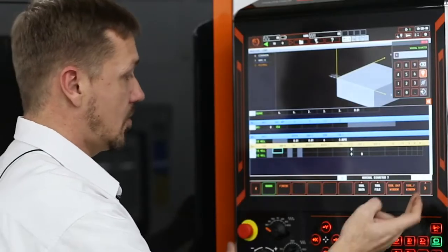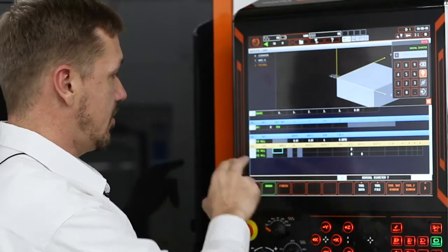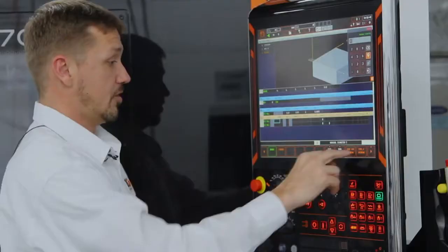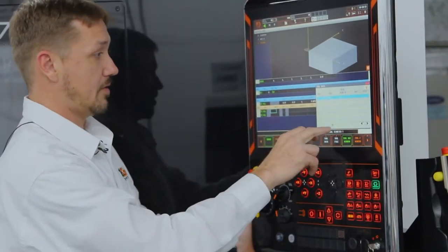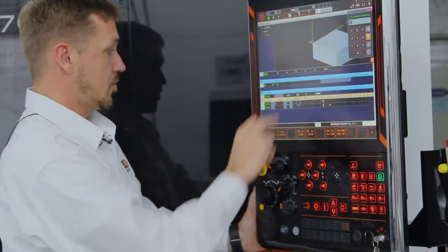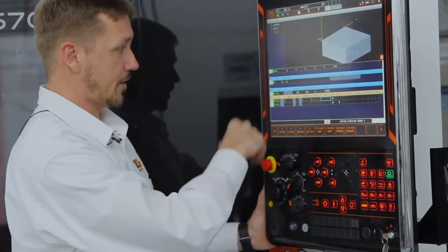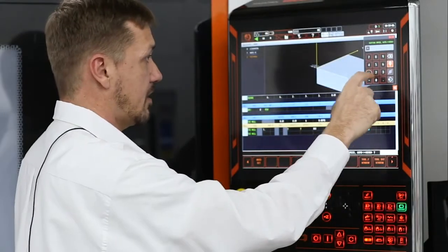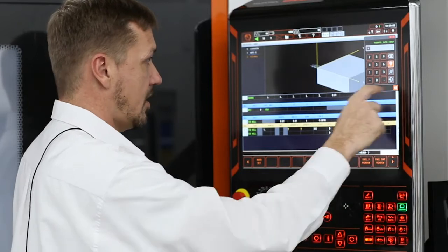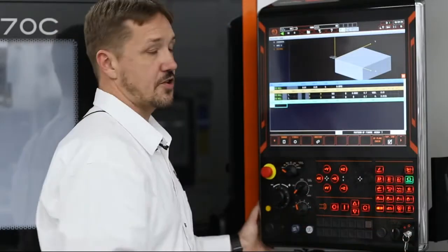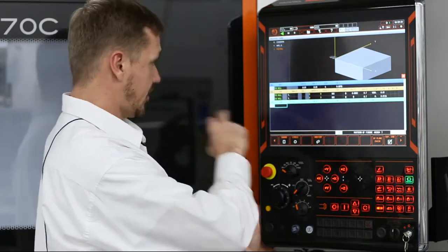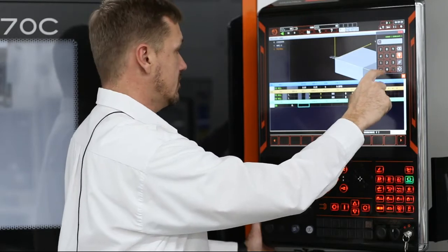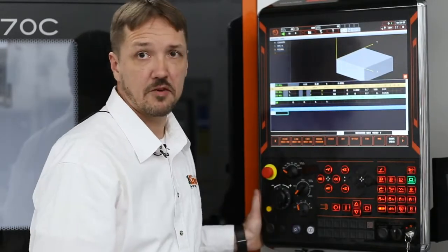So now, we know what kind of process we want to use. Now what kind of tool do we want to use to do it? Again, question and answer. So we look up our tool data. We've got a 1 inch face mill there. We'll just auto set all of that according to the type of material it is. We'll set a cutting speed of 1,000 and a feed rate of 10. And now I'm into the shape I'm trying to machine. So in this case, I've got a square. It starts off at 0, 0. So now we've just faced the top of our part.